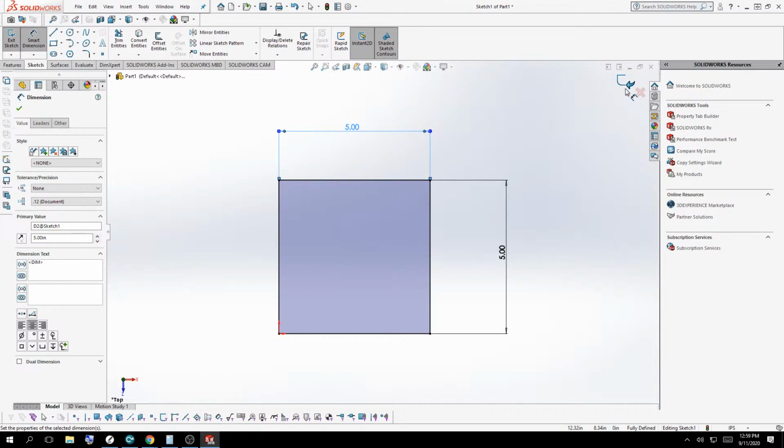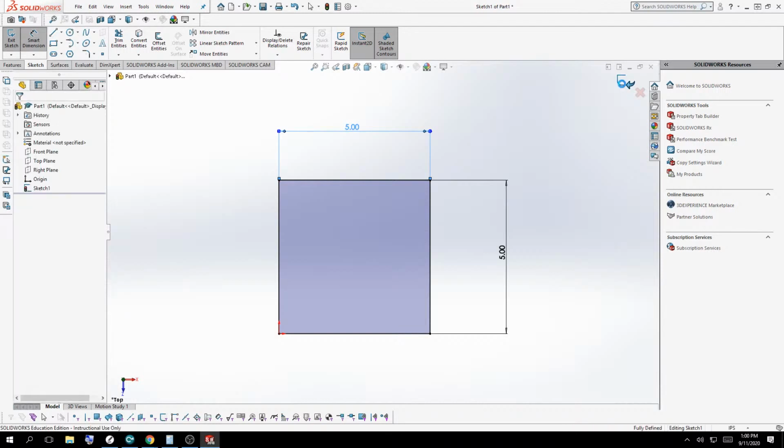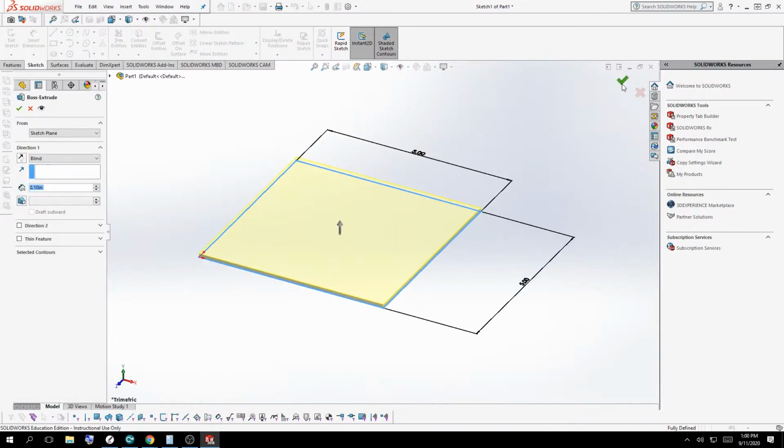What I recommend doing, obviously, to move on to the next step, to get our 3rd dimension, SolidWorks remembers that we are still interested in doing a feature that we started this video with. If you click the blue arrow, SolidWorks will automatically rotate into the solid 3D view at this point. If you somehow missed a step or backed up a few steps or hit Control Z to undo something, you most likely won't see this and you'll just see a 2-dimensional sketch. I'll address that in a moment.